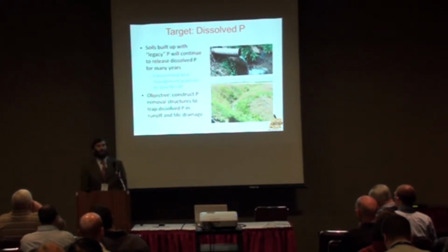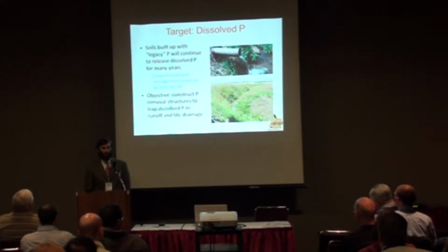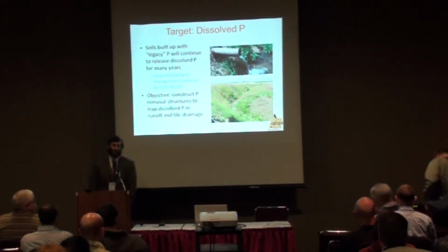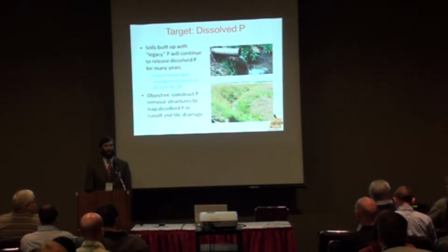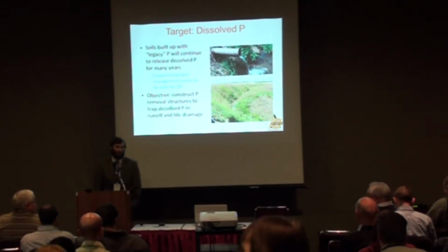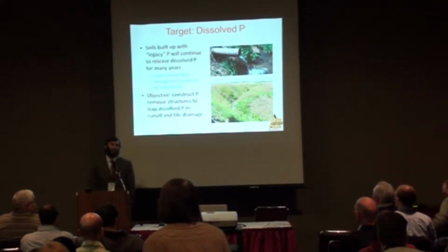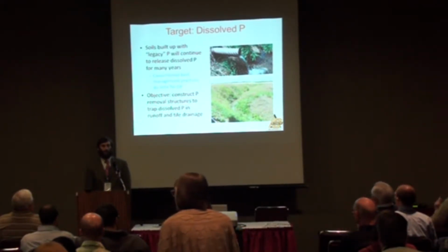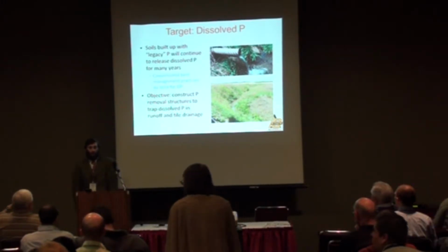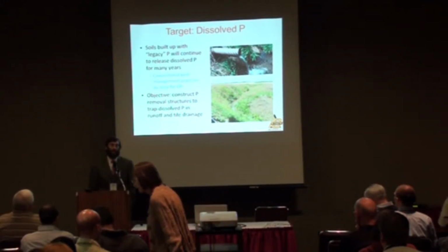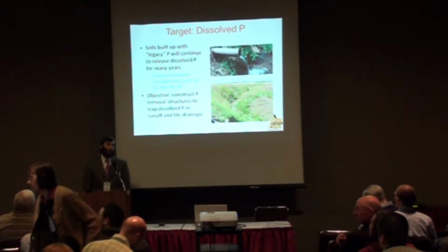The problem is that most of our best management practices are only able to address particulate phosphorus transport, that is, the phosphorus bound to solids. They're generally not able to do much for reducing dissolved phosphorus transport. Generally, any type of best management practice that can reduce erosion is able to reduce particulate phosphorus transport. Not true for dissolved phosphorus.